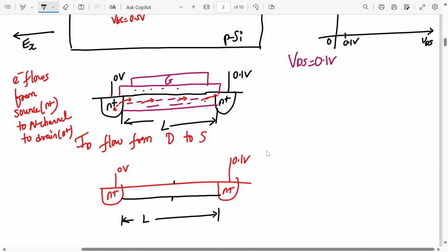That means here, gate to channel is how much? Here at the source end, with VGS and VDS there is a difference, right? VGS is the same throughout, right? See, VGS is the same 1.5 volt throughout. And to form the channel, how much is needed? VGS minus VTO should be greater than 0. So around how much? 0.5 volt. Do you agree? So how much is VGD? VGD and VGS. How much will VGD be? VGS minus VDS. How much is that?